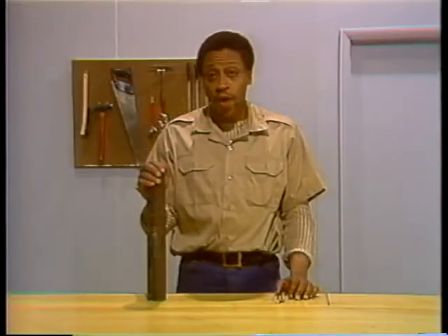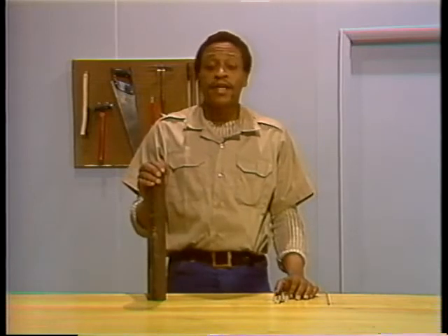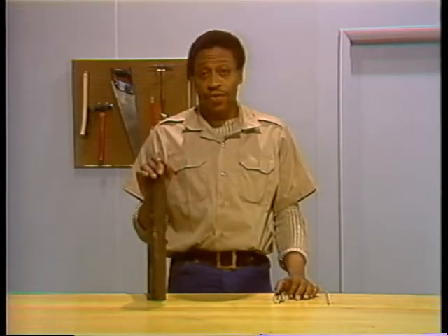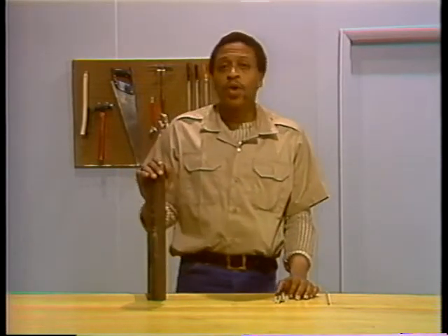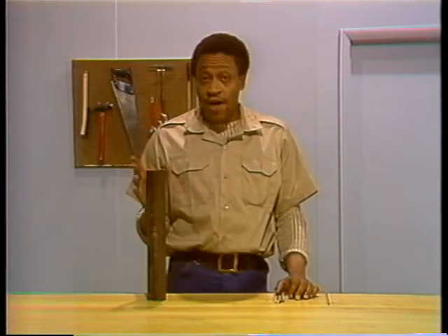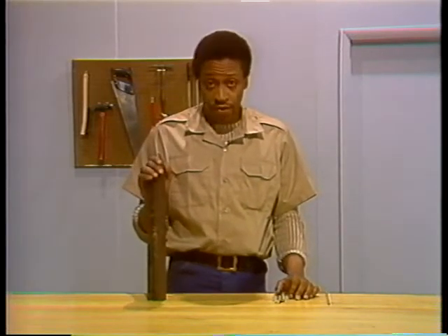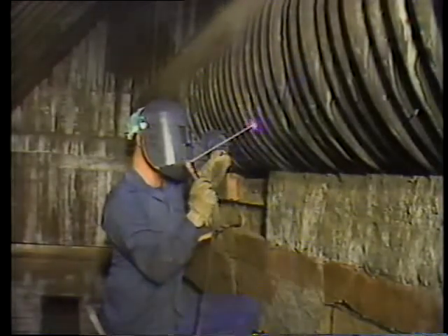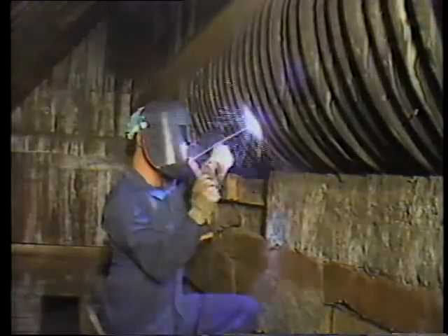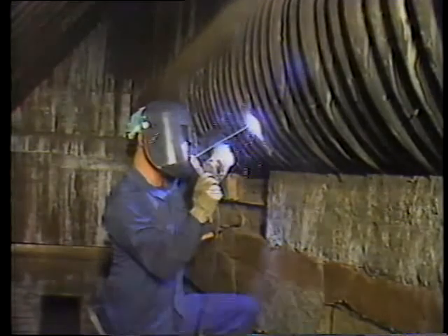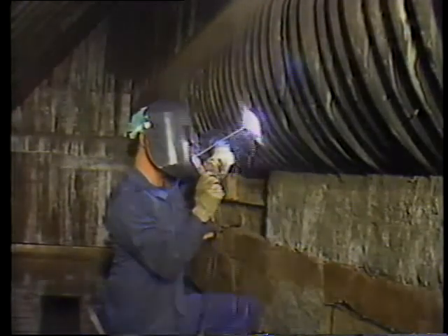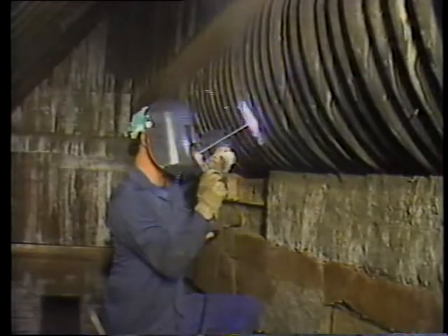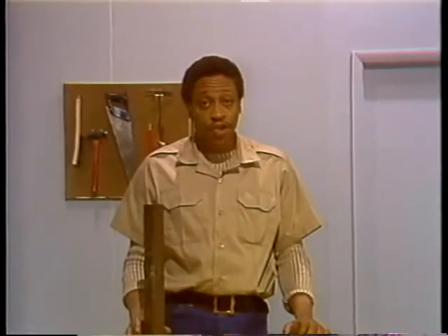Knowing why a tube fails and what to do about it is important because it is essential that failures be repaired. What we're going to do now is take a look at some ways of fixing boiler tube failures. All the repairs we'll be dealing with require welding. In a boiler, this work must be done by a certified welder. However, as a maintenance person, you may have to assist a certified welder, and you'll need to know how the repair is done. Remember to review welding safety precautions before work is started.